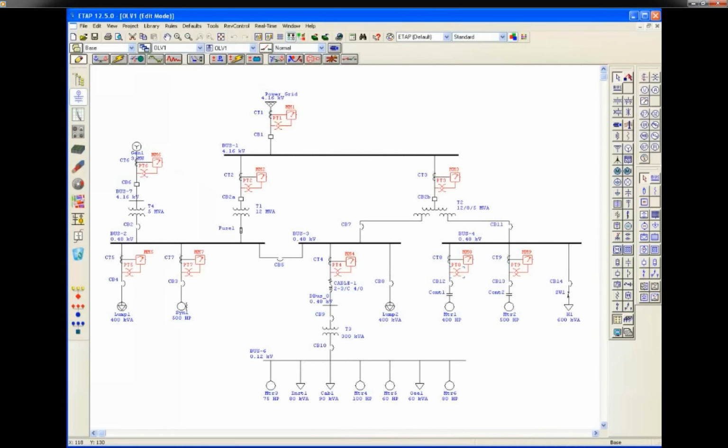After running the load flow study successfully, we can see any pending issues to be corrected in the project alert view. The alert view provides a red bell for critical warnings, or a yellow triangle if the study is fine. We may use ETAP to correct any sizing issues prior to sending the project back to SPEL.